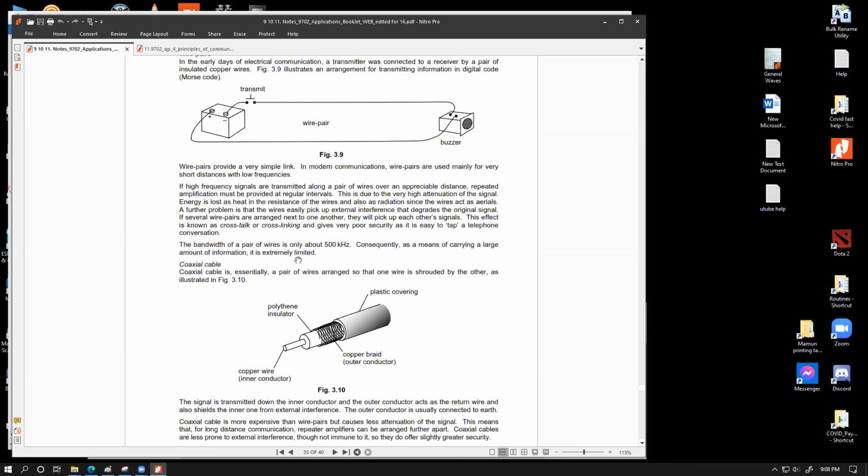A couple of things I would like to tell you is that cross-linking or crosstalk is the type of communication whenever you have unwanted, that's the important term, whenever you have unwanted connection across two communication channels which are placed side by side, or you can say that the information passing through one of the data channels somehow entered the other data channel unexpectedly. That's what we call crosstalk.